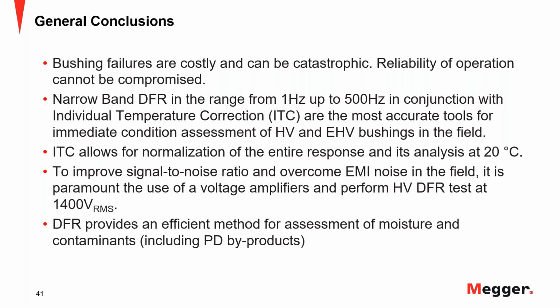To improve the signal to noise ratio, if you can see, don't try to analyze signatures where you have ups and downs on your dielectric response, especially at lower frequencies. Please don't do that, because you may get into completely awkward analysis and misleading assessment. The way to go with that and to overcome the noise is to apply a voltage booster or an amplifier and improve the signal to noise ratio.